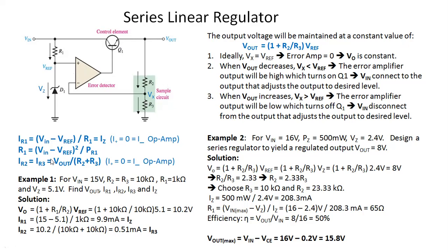So here, if we have these values, ideally we can calculate the output voltage according to Ohm's law, according to the voltage divider rule. How will you get it? The input voltage here is V reference, and we calculate the output voltage across R3. So you can take R3 upon R2 plus R3 into VREF.